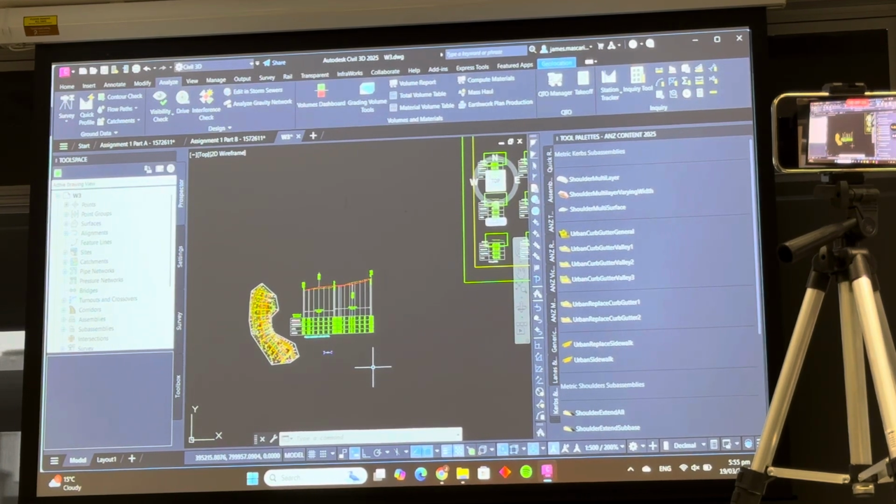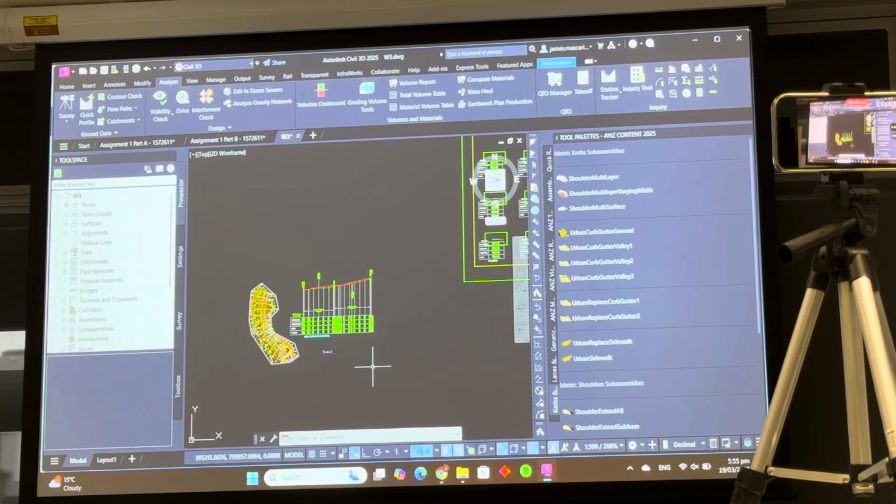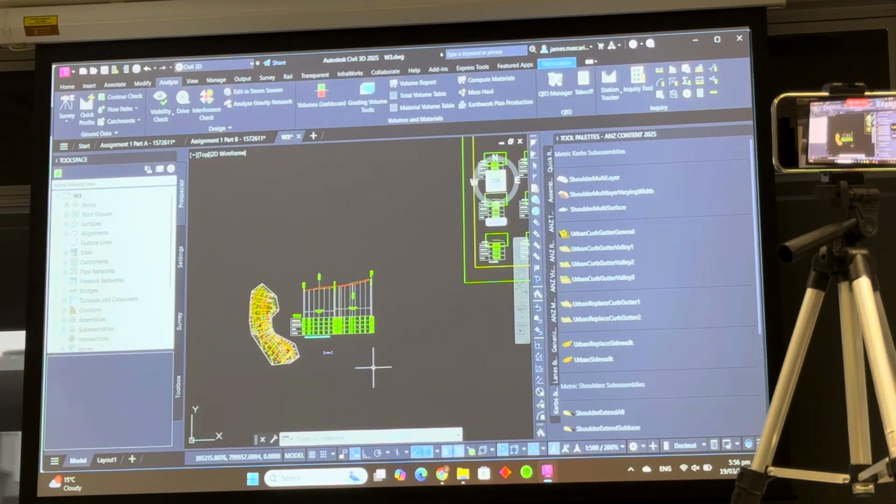Once it's in AutoCAD, you can do that, no problem at all. You change everything to flatten everything off, so you can now use it as an ordinary AutoCAD file, okay? And that was some of the problems that you had hatching in your very first assignment for me last semester, because it wasn't hatching because some of the points were still in 3D. I did that purposely to make you redo the boundary, and it's what happens. Survey companies give you data that's still in 3D.